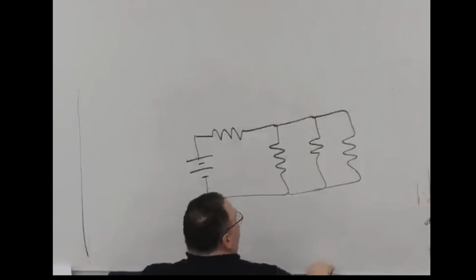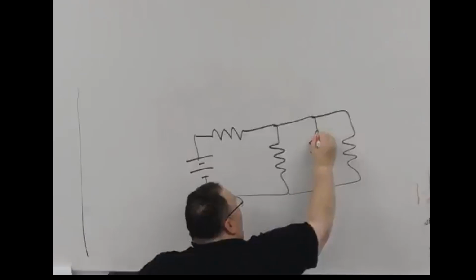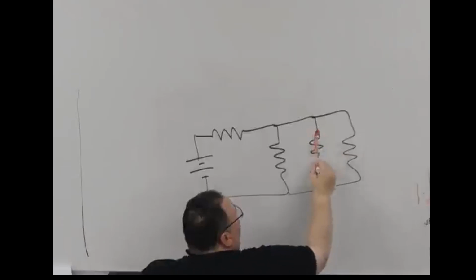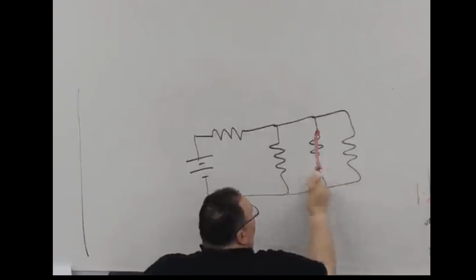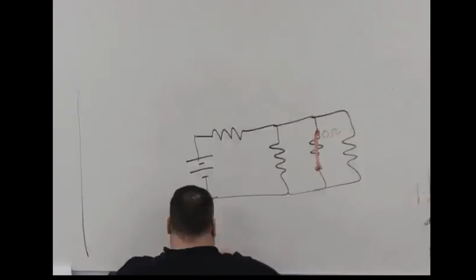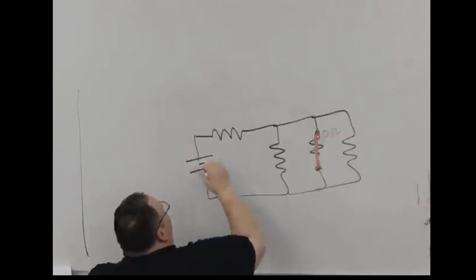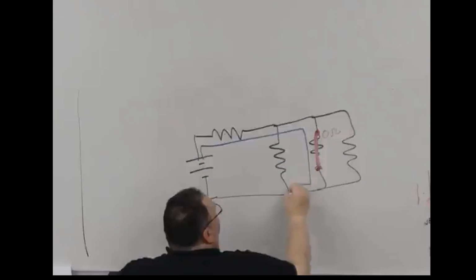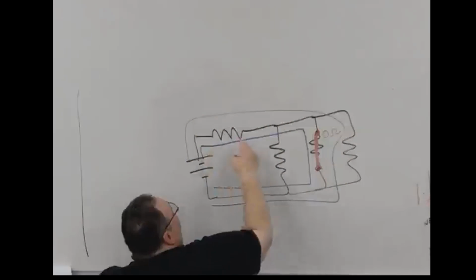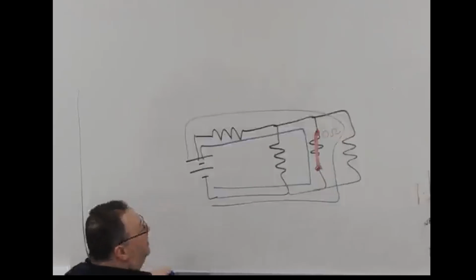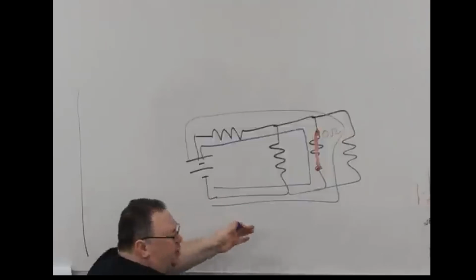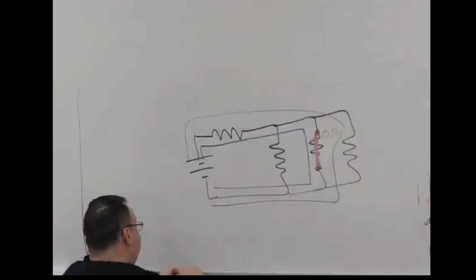So without doing any numbers, if I short out this middle resistor here, well, this acts like a piece of wire. These two resistors in parallel with this will be 0 ohms, but I still have this mainline resistor, so my circuit will essentially consist of just this main resistor here. So I can put a short in and I can measure it and I can do some comparisons.